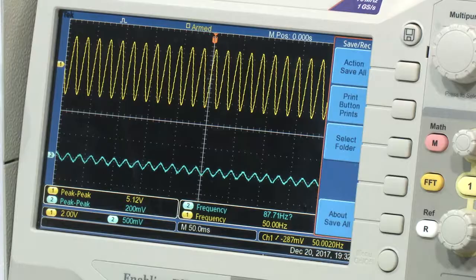Now, what we see is my frequency is 50 hertz. What was my low frequency FL? My low frequency FL was 159.15 hertz. So, this is 50 hertz, so it will not allow, and that is why you can see the peak to peak voltage. Look at this, 200 millivolts, not allowing, it is very clear to see, right. It is suppressed, that is what we have discussed. The output signal is completely suppressed below FL. It will also get suppressed above FH, we will see that, alright.